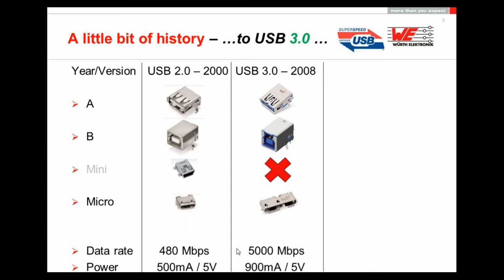So to figure out in what mode we are using our device, we need this OTG identification, which we can see here for the mini and micro with pin number 4, to figure out in which role we use our device.